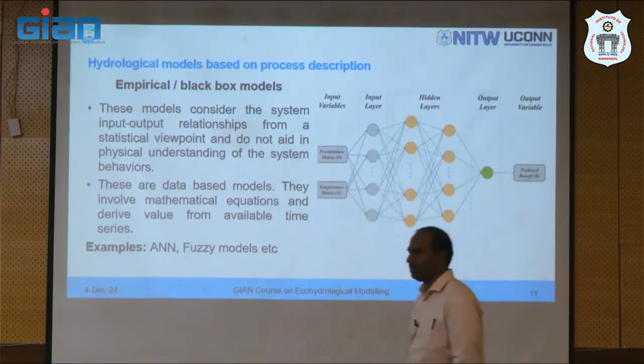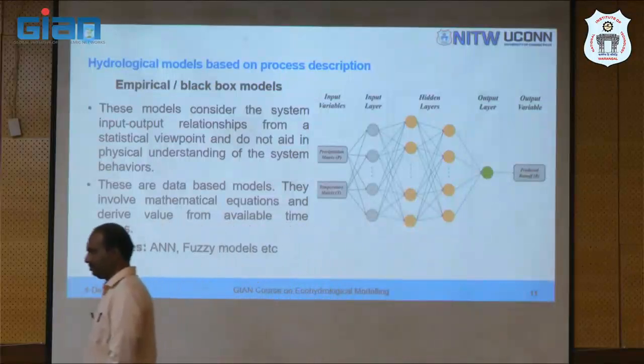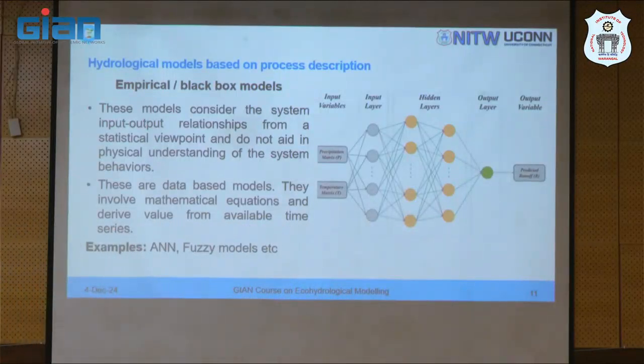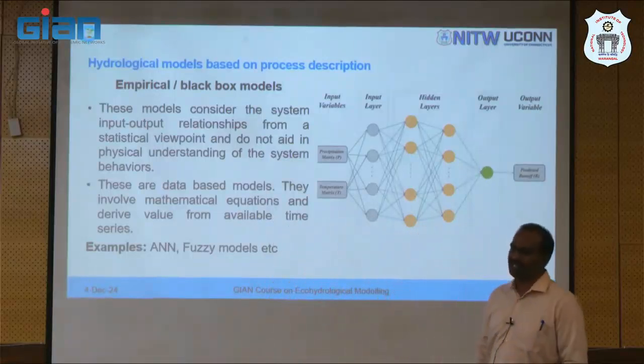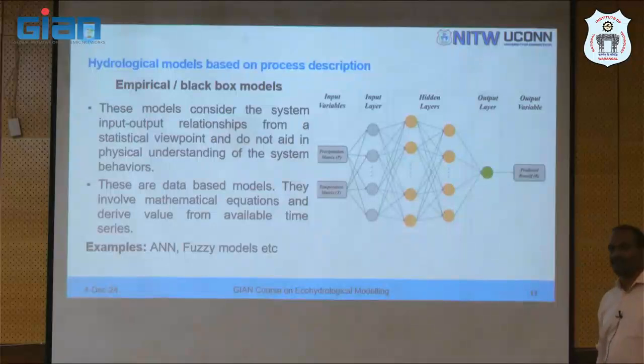What about Penman-Monteith? Is it empirical, conceptual, physics based? How many of you say Penman-Monteith is physics based? Remaining are not sure. It's physics based. It is derived using conservation of momentum, conservation of mass and conservation of energy equations. Penman-Monteith can be derived by applying the Reynolds transport theorem. Okay.